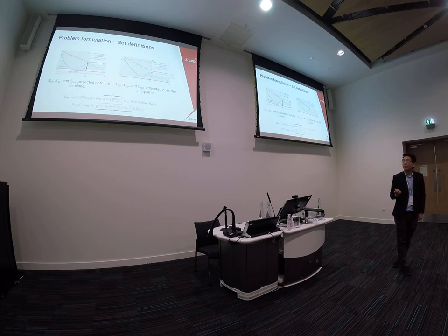We don't care about the part beyond the net. We only care about the real trajectory until the net. But we need an extension for the controller to track. That's why we have the extension also from here. And in the generation task, we have a constraint tightening technique. We constrain the state to be smaller than what we want, so that in real life with gusts, the state will stay inside the red corridor. That's the idea.